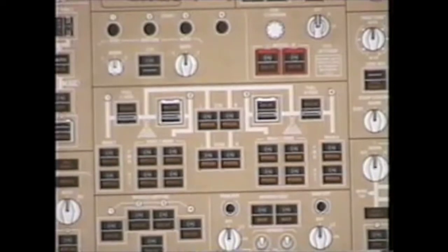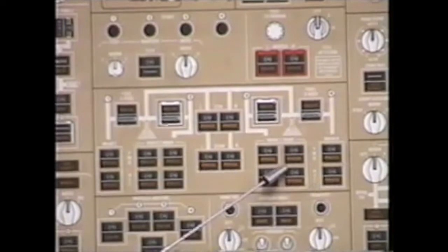Moving all the way over to the right is the fuel transfer main tanks 1 and 4 switch, primarily a maintenance switch. This switch, when pressed, opens transfer valves between main tanks. Pressing that switch allows gravity transfer between main tanks 4 into 3 and 1 into 2. Maintenance uses that switch to defuel your airplane to get the fuel out of the outboard main tanks. The only time the flight crews will ever use this switch is per an irregular procedure, such as 2 boost pumps inoperative in an outboard main tank.